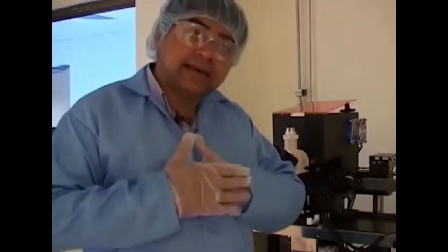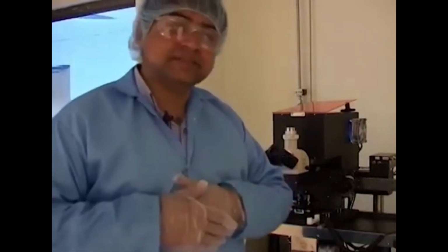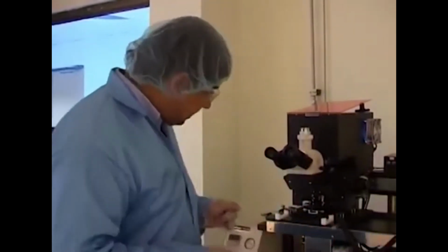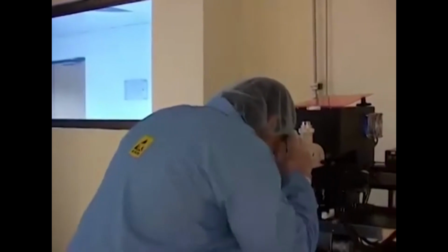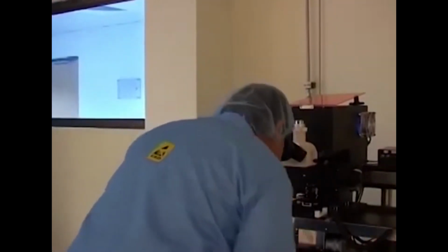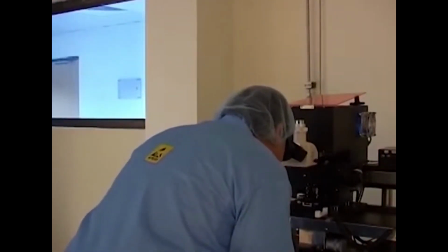Either event is not good for us. We have to just be able to make a close contact without much pressure onto the resist coated surface. One of the reasons why this kind of alignment system is also called a contact aligner. So essentially I would just like to see through this microscope stage and find out if the features are close. I see that there is a little bit of displacement needed on the z axis so that the images can be correctly focused.